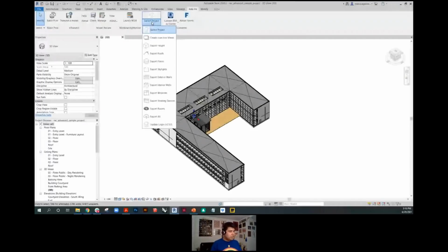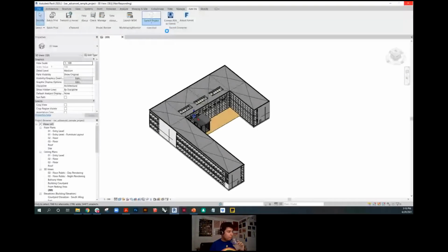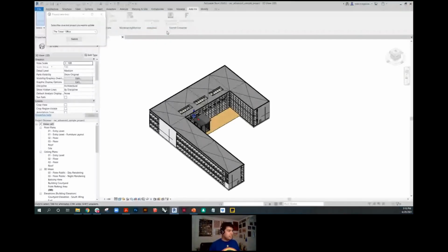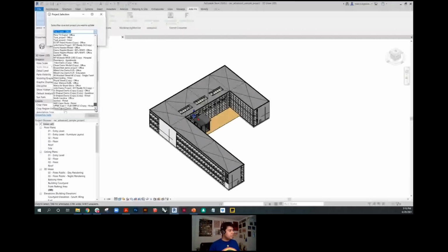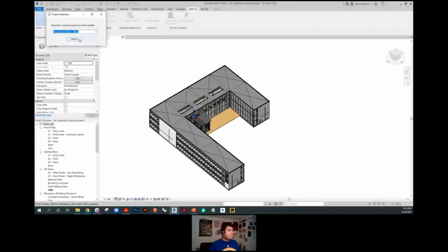Step 2, select our project. Since we've just created our project, it should be located at the very bottom of the projects list. Some other notes while this loads: cove.tool is primarily looking for geometry that would be part of the architectural model. So you don't really need the engineer's model or the mechanical model when you're exporting to cove.tool.